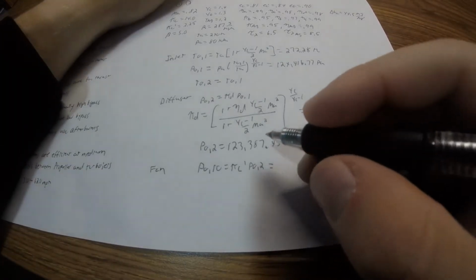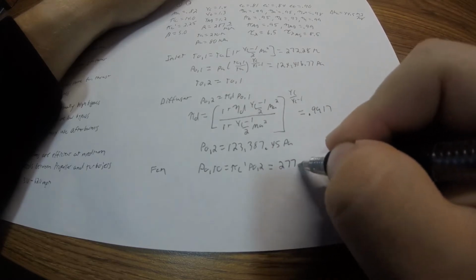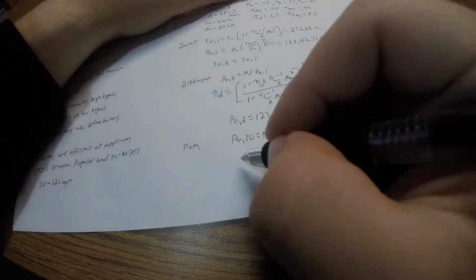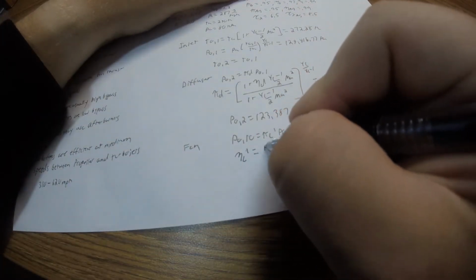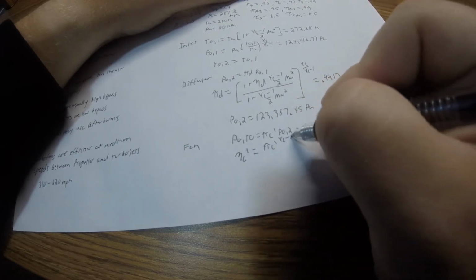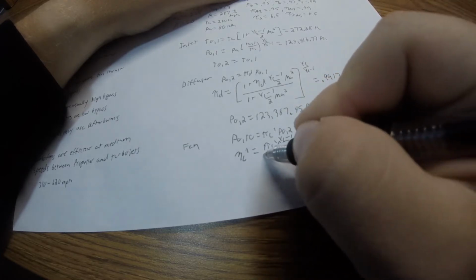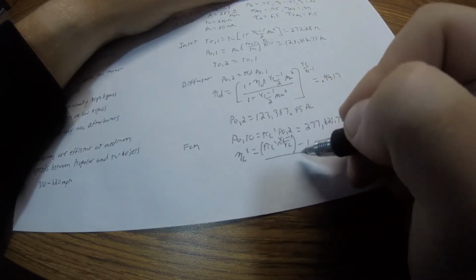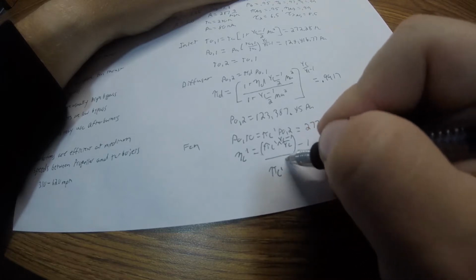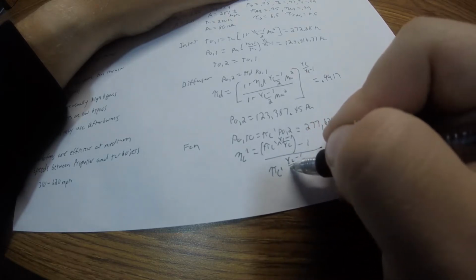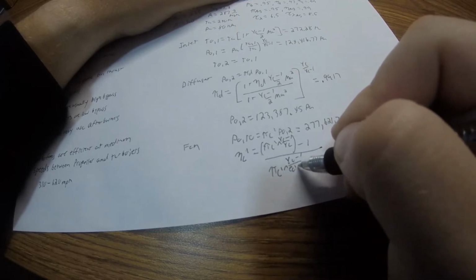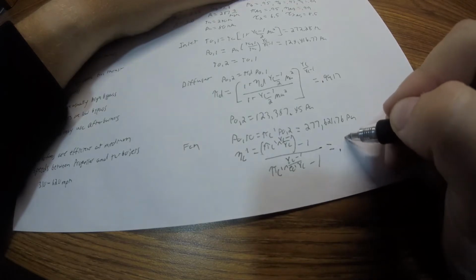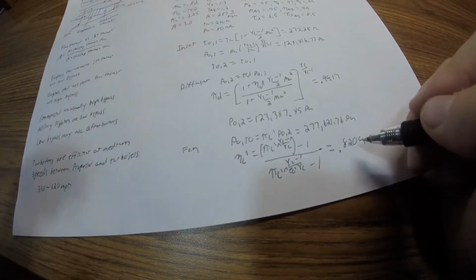So it increases by 2.5 to that pressure. We have the efficiency of the compressor, and this is raised to that value. Then all of that minus 1 over pi c prime, polytropic efficiency, and then this is raised to this. The efficiency of the compressor and the fan, 0.8209.